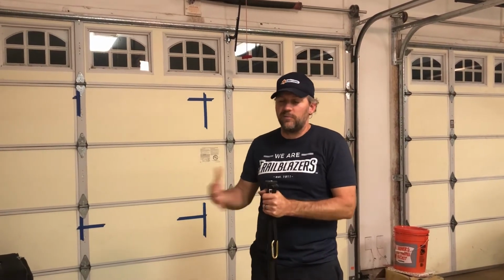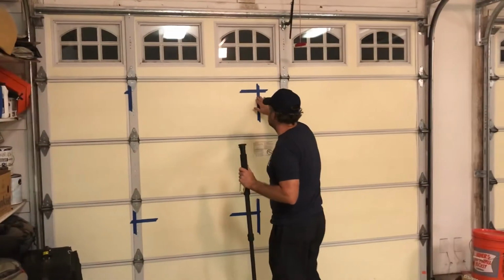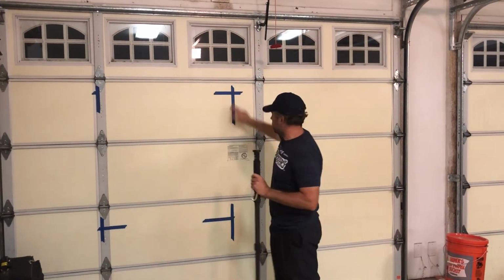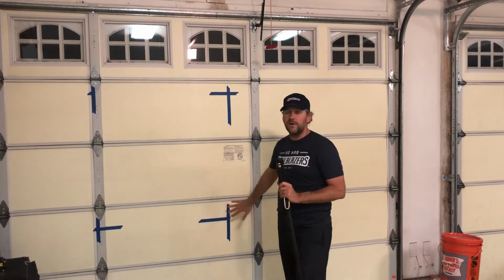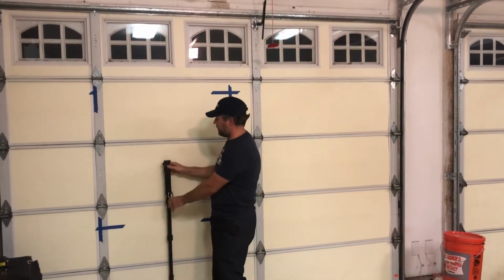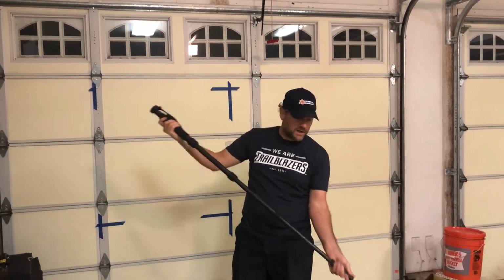So in order to match a virtual Blender camera with a real-world camera, it helps a lot to know a few things about where our camera was and what it was photographing. Specifically, we need to know three things. We need to have an object of a fixed size, so I've measured out 1 meter from corner to corner and corner to corner. I've got a 1 meter square marked out on my garage door. I've also got a center mark here so that I know how high my camera needs to be, and I've got a monopod that's adjusted pretty close to that height.